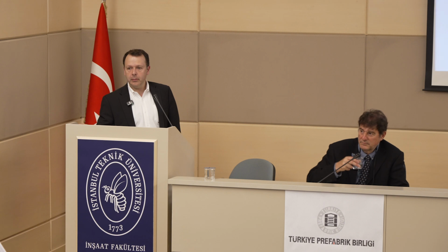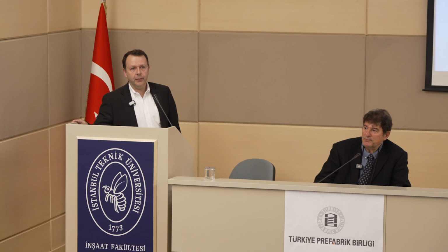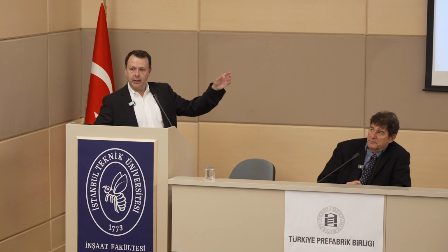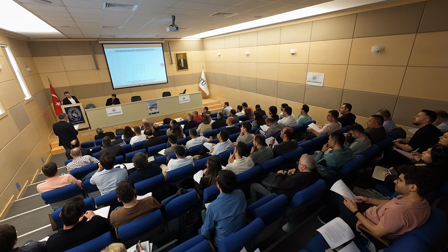Do you have this in ASCE 7 also? For nonlinear analysis, do you still use the 0.7? Do you do some calculations? It depends on the software and the model that you're using, right? If it is a model like this with concentrated hinges, then in the columns we use 0.7.